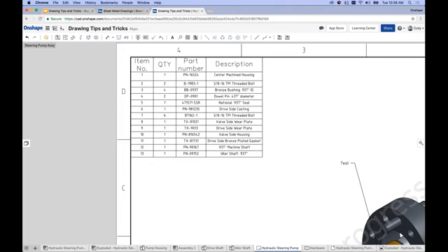I'm fairly certain of it, but please let us know, if anything, just so that we get an accurate count of the number of affected users. But I'm fairly certain the answer to your question is yes. It's showing the same callout information regardless of what stage in the hole, which part it is, right? Yeah. So same thing. This is specific to multi-part holes. So when you're creating a through hole, then tapped hole in multiple parts, that's where it's most applicable.